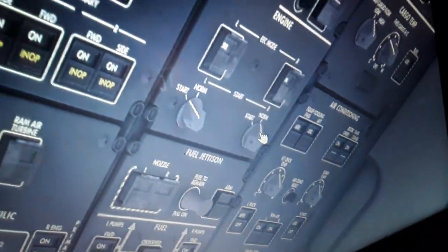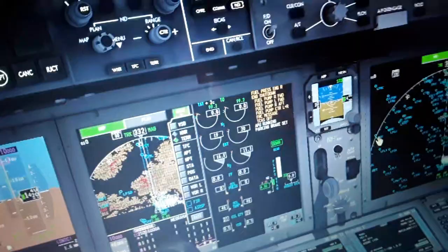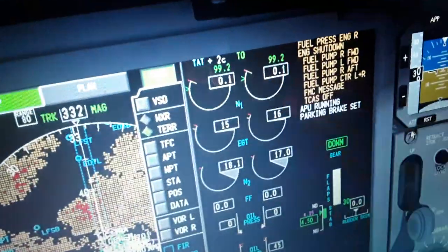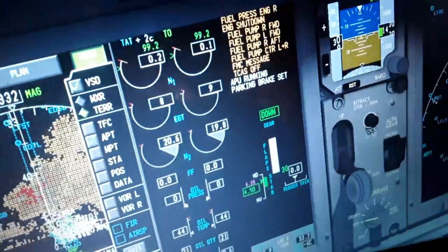Also the hydraulics. So we go here in the overhead panel very quickly and restart the engines. Auto start in the on position turns on the FADEC, the full authority digital electronic control computers that control the engines. You can see dual channel redundancy, if one channel fails, the other takes over. We have 20% only, pressurized right now to the engine.